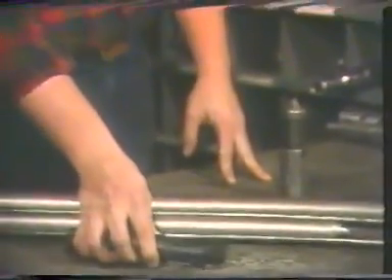In addition to the specialized subsurface production controls run into the tubing with this work string, there are several other commonly used tools which may be run for routine operations. For example, the first step in performing any wireline operation downhole is to determine if the tubing is clear to the depth at which that operation is to take place, and if not, to clear any obstruction from the tubing.